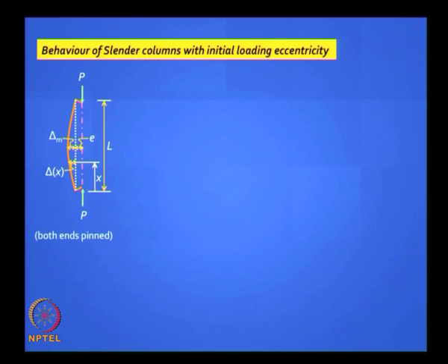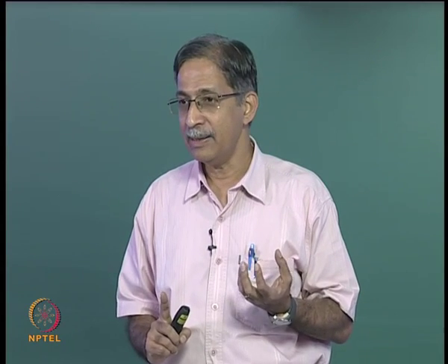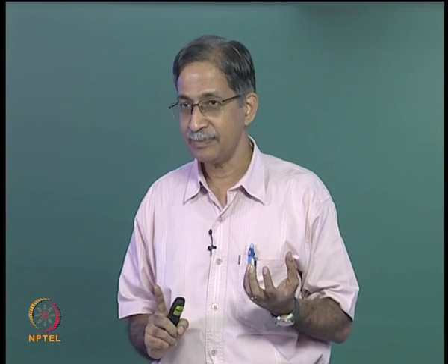Okay, now our real interest is not so much column as beam column, right. So we make our first entry into beam columns by looking at structures like this. Take a look at that, okay, that is a channel shaped structure in which I apply P eccentrically. That value of E, eccentricity, is called primary eccentricity, right, but the more I press there, the more it will bulge outward, so I get a delta in addition to E. If the column is very stiff, that delta will be close to 0. If that column is slender, that delta is going to be significant. Does it make sense?